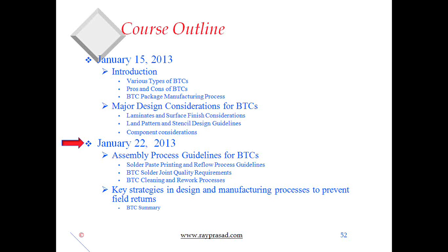What I would suggest depends on what the pitch is, because the ball is 40 micron. That means the pitch of this thing is very low. Now we are getting into a different area, where you need absolutely the best printer money can buy.